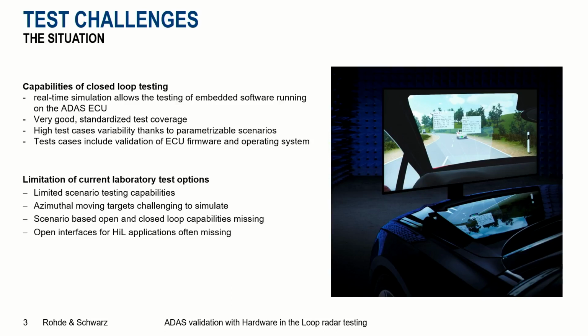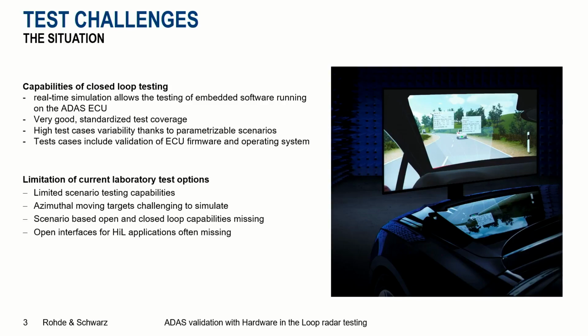The current capabilities of closed-loop test systems are that real-time simulation allows the complete testing of embedded software running on the ADAS ECU itself or on the radar sensor under test, whether it's a more, let's say, basic system. It also provides very good standardized test coverage. What does that mean? Let's say you have a test catalog like Euro NCAP, and you can test or validate the radar sensor's functionality before even going to a proving ground with a vehicle where the radar sensor is installed. Further, there is a very high variability of test cases.